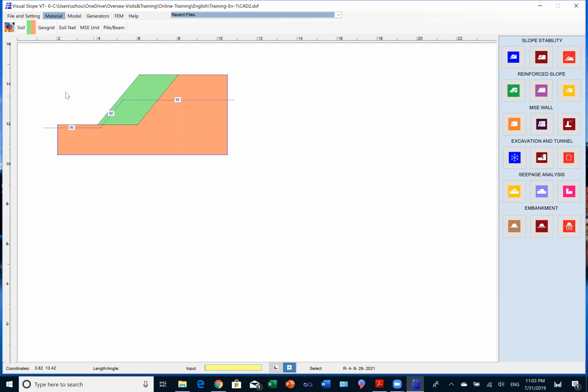But also when you click that, say here, you want to see the coordinates, it's 4 and 12. Actually, we need 40 and 120. So AutoCAD made it 10 times smaller. So we have to rescale it. There are 2 different ways you can do. The easy way you can do is going to here and do the scale.